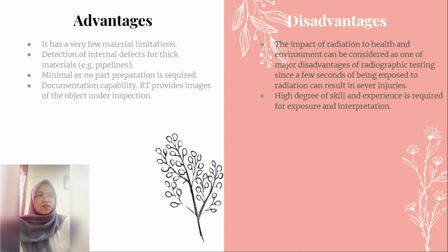The disadvantage of RT is that the impact of radiation on health and the environment can be considered one of the major disadvantages of radiographic testing, since a few seconds of exposure to the radiation can result in severe injuries. A high degree of skill and experience is required for exposure and interpretation.